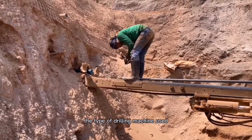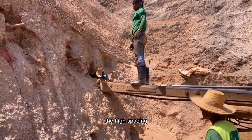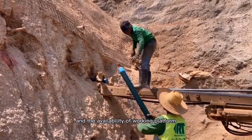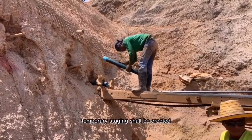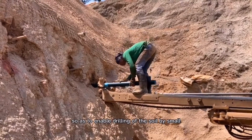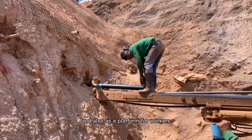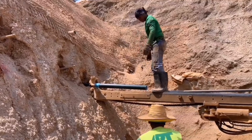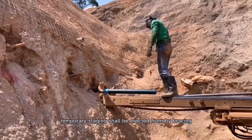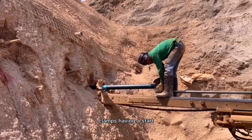The type of drilling machine used shall depend on the slope profile, the height, spacing, and the availability of a working platform. Temporary staging shall be erected along the slope side so as to enable drilling of the soil by a small portable drilling machine, and also as a platform for workers. Temporary staging shall be erected by bracing pipes fastened together by pipe clamps.